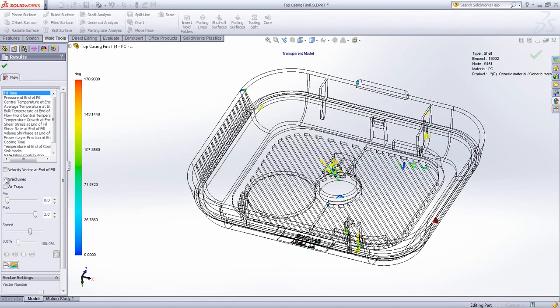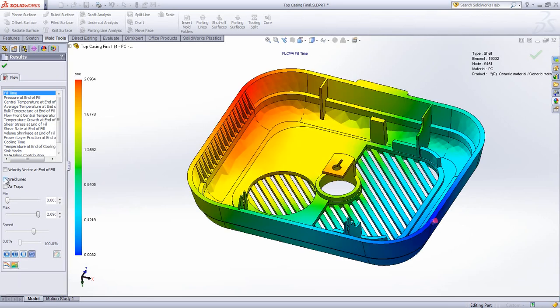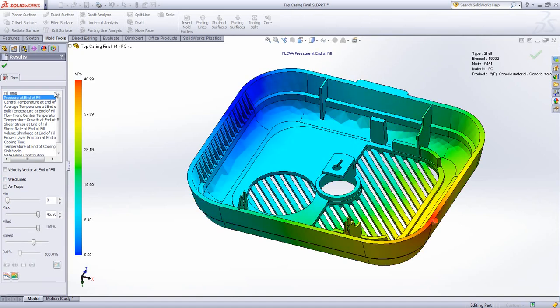The new injection location definitely helped us reduce significantly the weld lines, and we now pretty much don't have any weld lines on those ribs. However, you can see that with 47 megapascal, our pressure to fill is still somehow high. We still need to get this lower, considering that we are looking at a single part cavity, and the injection pressure requirements will increase when moving to a multi-cavity mold configuration with sprues and a runner system.